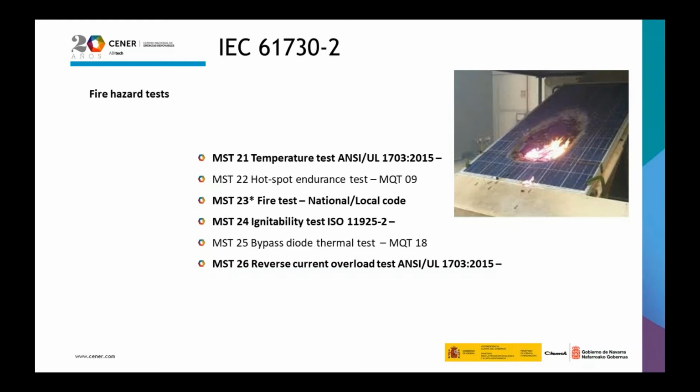The ignitability test determines the capability of the module to resist direct small flame impingement. And the reverse current overload test is intended to determine the acceptability of risk of ignition when the module is operating under reverse current fault conditions.